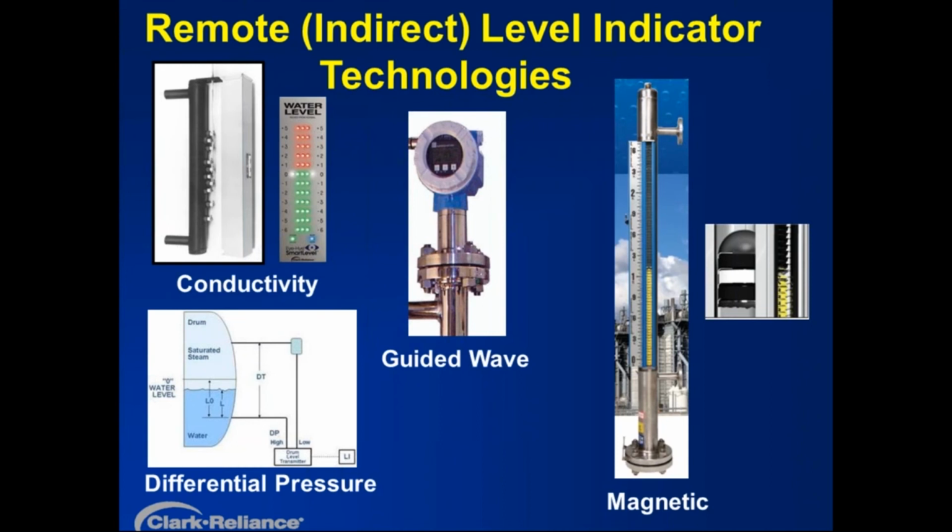We forecast more guided wave being used for control, and the conductivity probe having all the redundancy of the individual sensors and the fairly large indicator for the operator. Operators really tend to report that they like that image and that device as their so-called reliable traffic light to operate the boiler. And as soon as something draws out a normal level, it gets their attention.